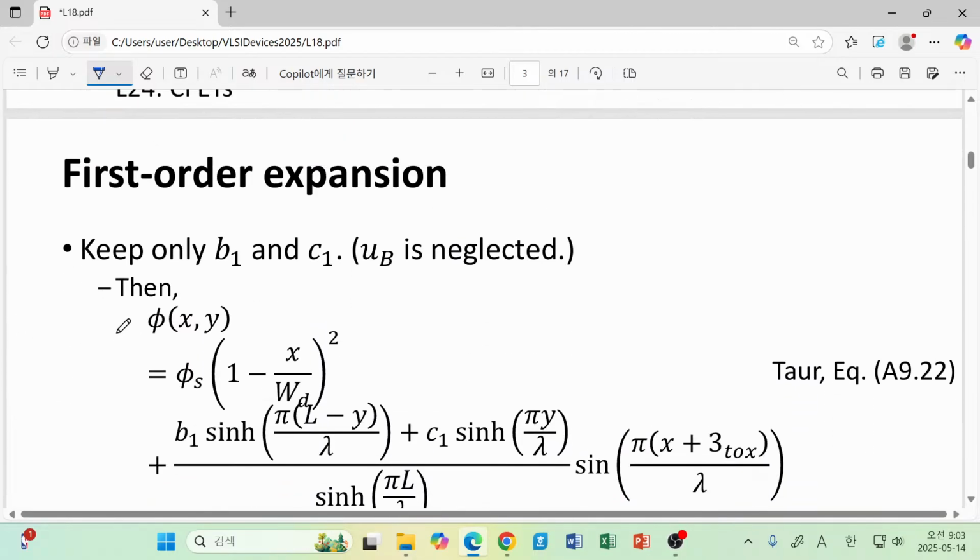Before talking about the velocity saturation effect, first of all, let's finish our previous contents on the short channel effect. If you remember correctly, previously we had to solve the Poisson equation, which has just a constant density Na.